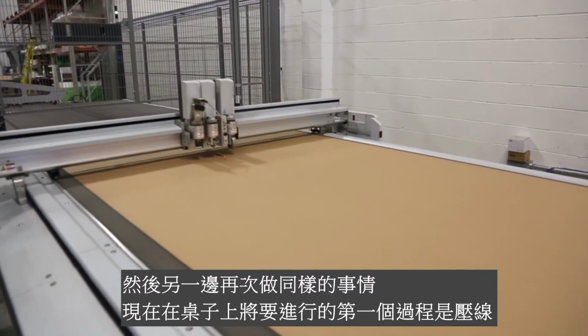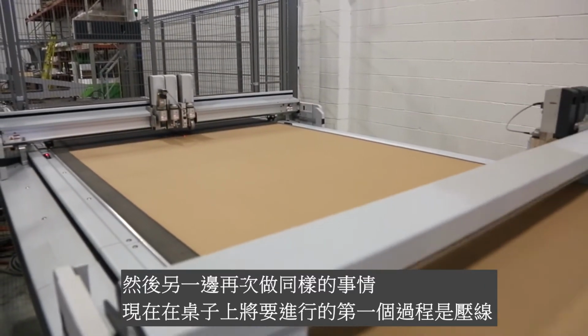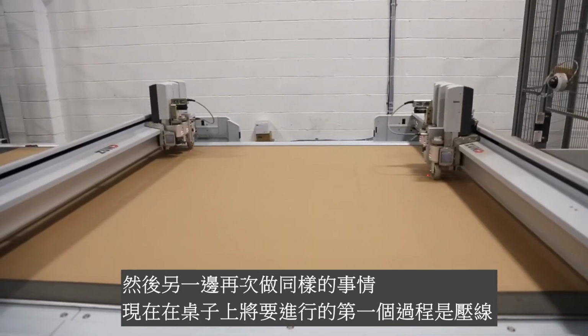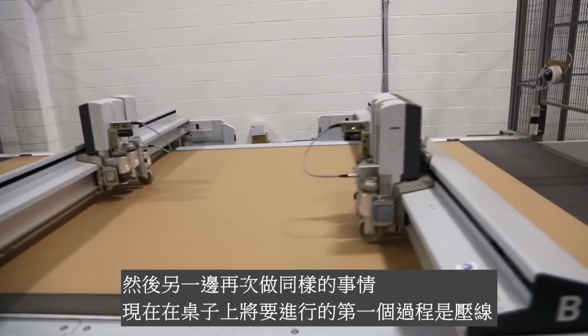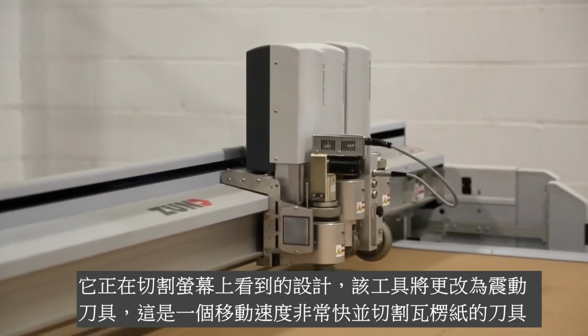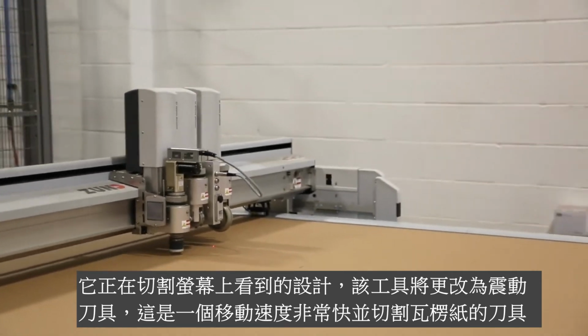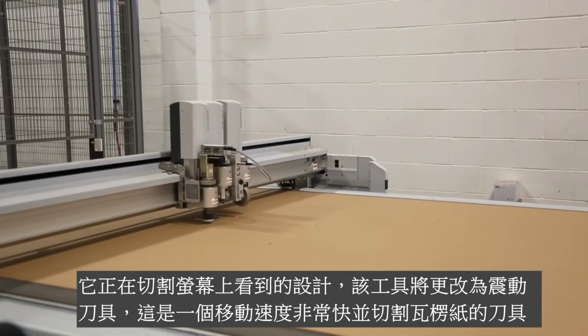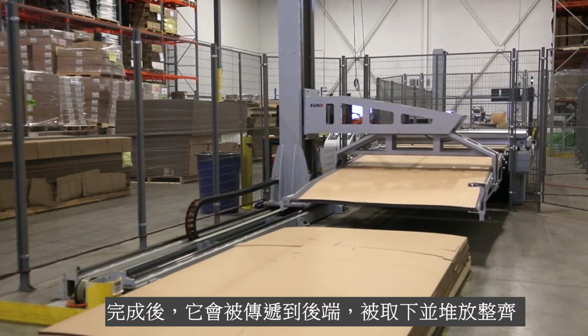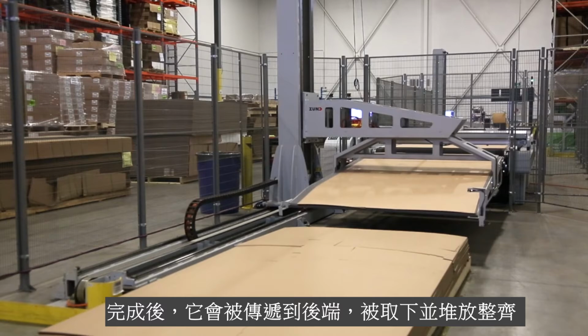So now over on the table, the first process that's going to happen is going to be the creasing. And it's cutting the design that you see on screen. Once the perfing is done, the tool will change to the oscillating tool. This is a blade that's moving very, very quickly and cutting through the corrugated. Once it's done, it's going to get passed over to the stacker. It's going to lift up to the off-take and stack on the pallet.